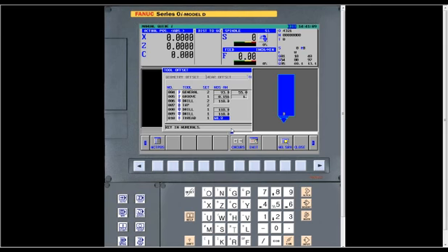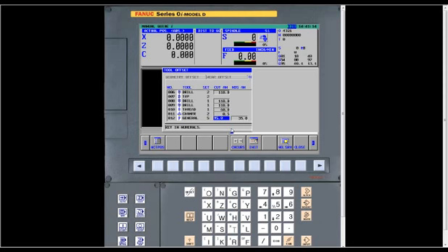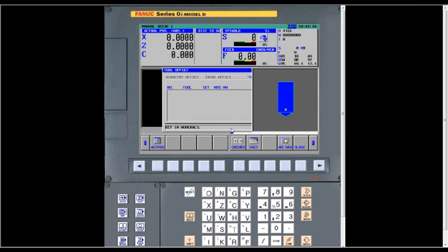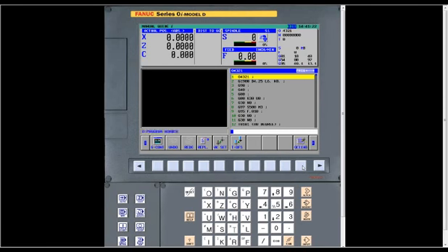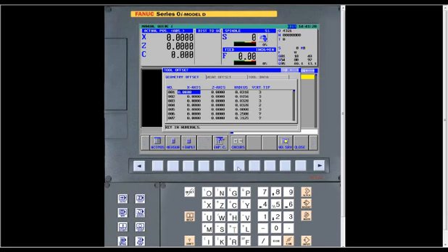Very simple. But it's critical that you get this information correct beforehand. Then a chamfer tool, general, and then a flat end mill, again, just the orientation. So that's all the information that we typically would put into our tool offset data.